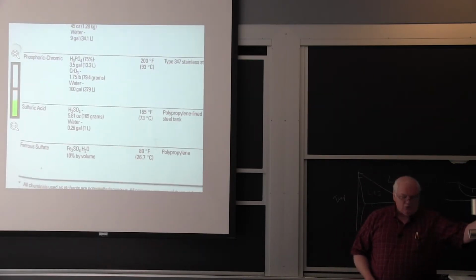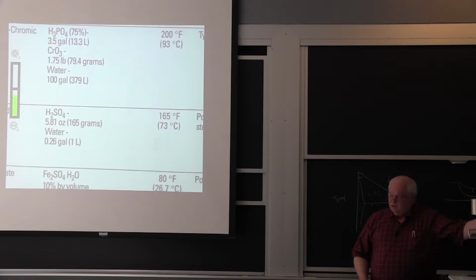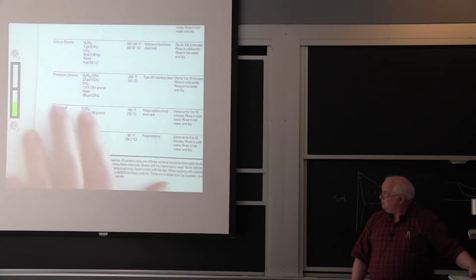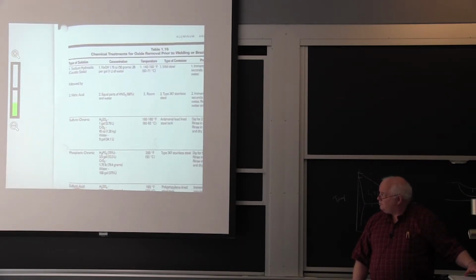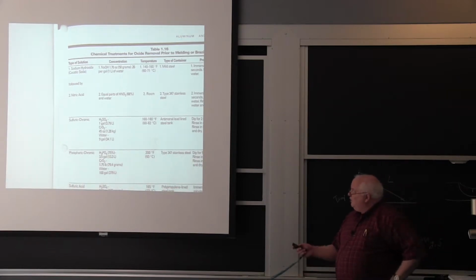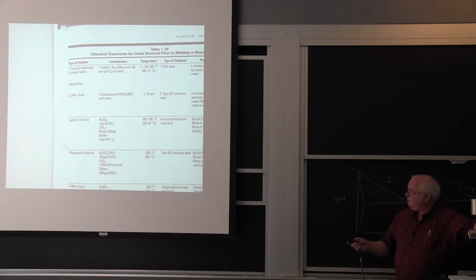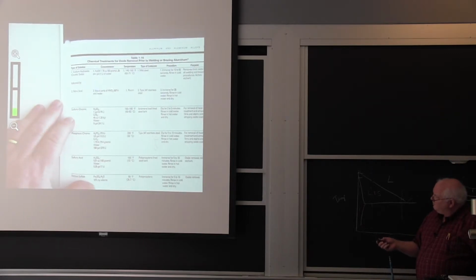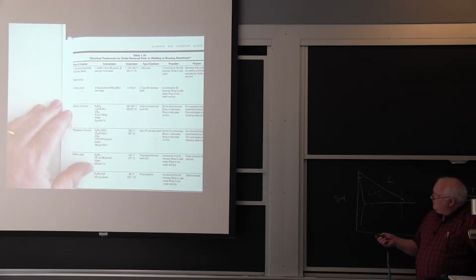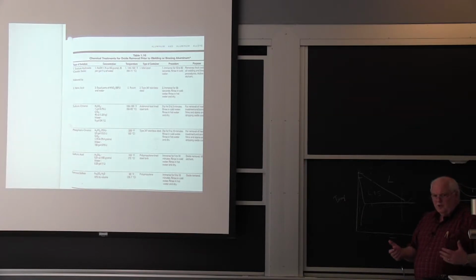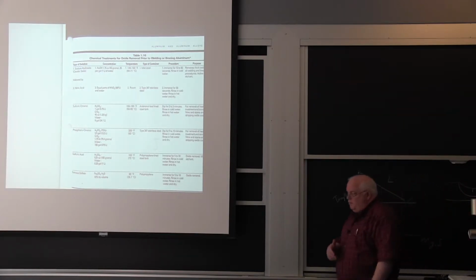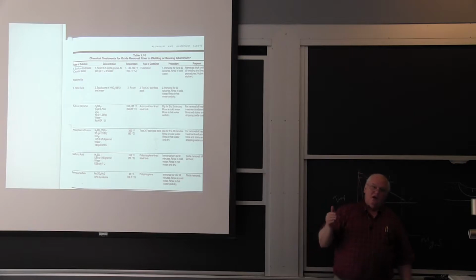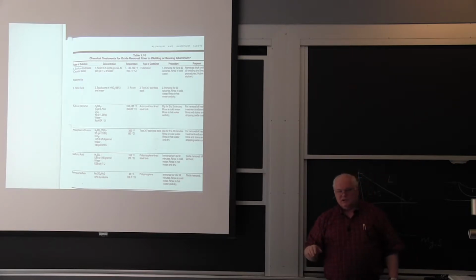That aluminum oxide is what gives aluminum its corrosion protection, gives it high temperature oxidation resistance, which we use in many alloys like the nickel alloys and stuff. We add aluminum to give it oxidation resistance at high temperature. You have to clean the oxide off the aluminum if you're going to weld well. Aluminum oxide melts at 2000 degrees centigrade. Aluminum melts at 660 degrees centigrade.